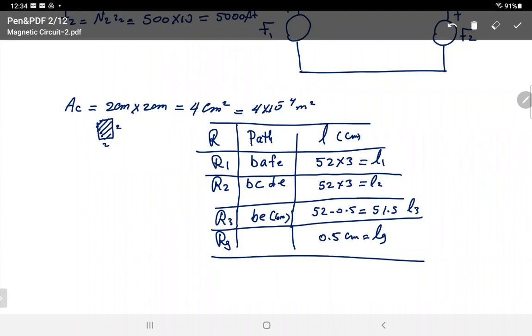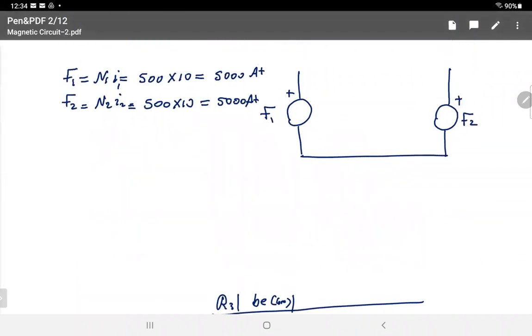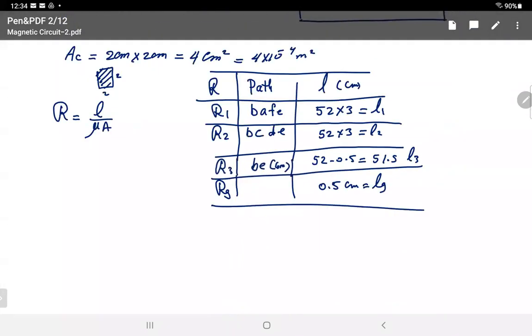Once you did that, everything is solved, because they are doing that to calculate the reluctance, which is analogous to the resistance of the circuit. So what you're going to do? Well, we know the formula, the reluctance is equal to L divided by mu A. You have A and you have mu, we just calculated it. That's on the previous page.